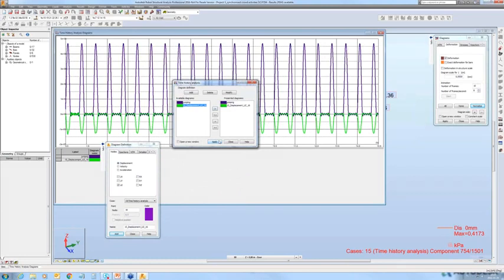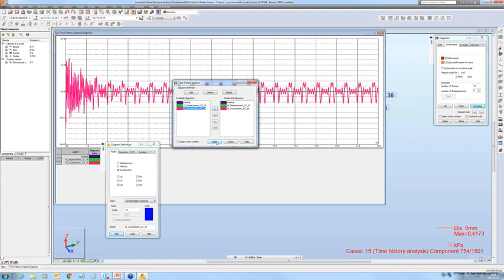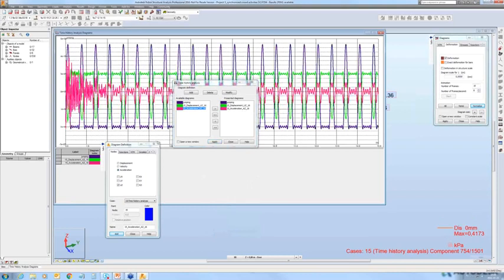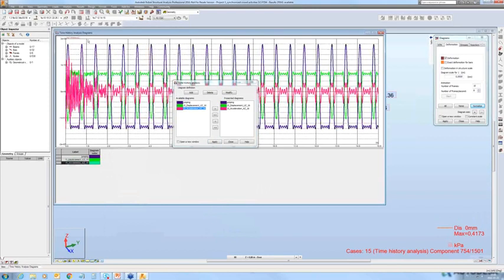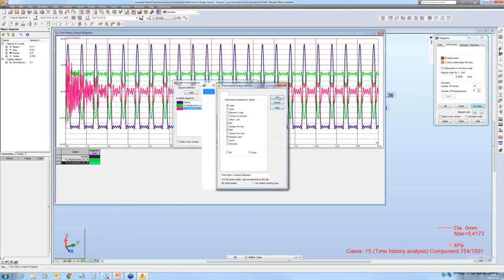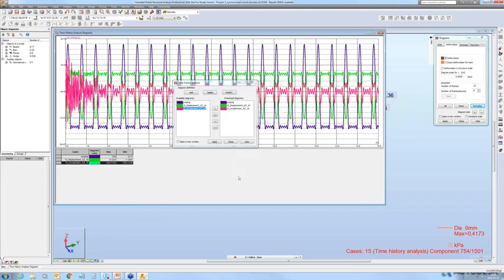Okay, you can see. And we can also add the corresponding acceleration. We can change the color, for example. So we display that on our diagram. By default, the scaling is to the largest value, but we may switch off this scaling, and now you can see that each value, when you click on the table, has its own units. And we may also add the information about maximum and minimum value for the displayed results. Okay, so let me go back to the slide.